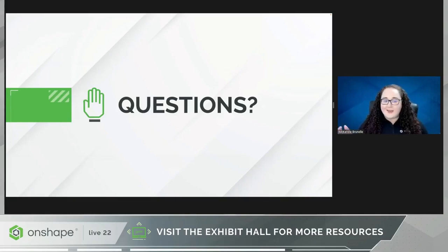Once you get the Onshape models and documents set up, I would look at what MKCAD did as far as creating the application. They've made the code they use for that public. They posted it on GitHub, so you can use that as a reference if you want to make an application. The other thing I will say is for many of these components, you don't have to model them completely from scratch yourself. Most vendors will put up STEP files or something else that you can grab and import into Onshape. Then you can set up your library so that you can insert those quickly once you get them imported one time.